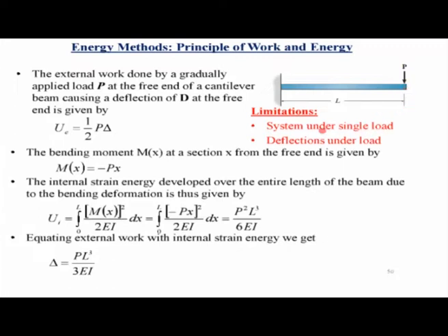Again, this method is limited to calculation of deflection under the load itself and under a single load at a time. If there are multiple loads, or if you want the deflection at some point other than the load point, then this method will not be useful.